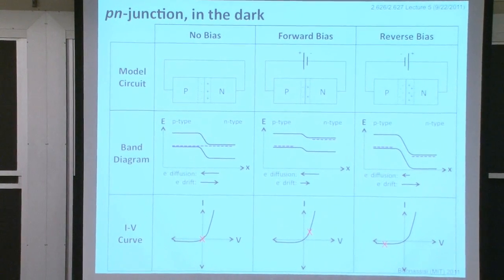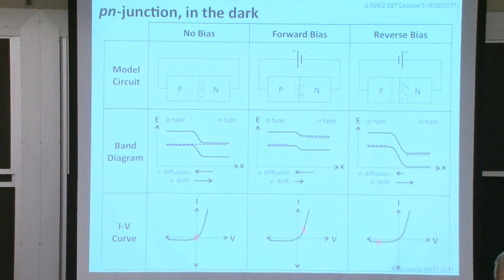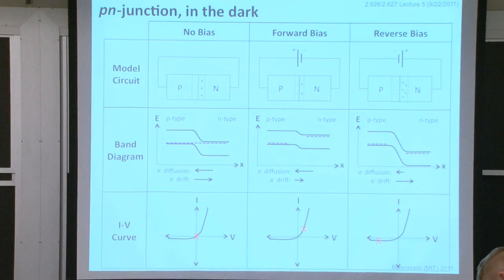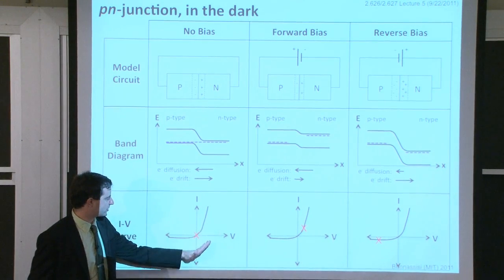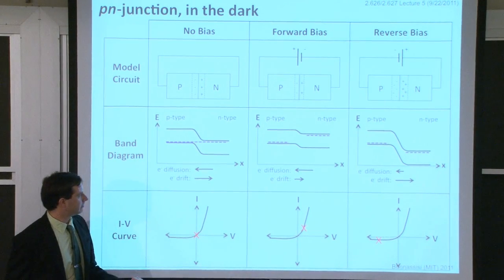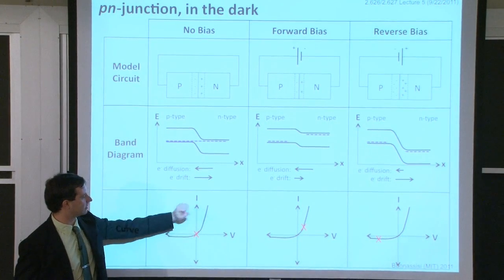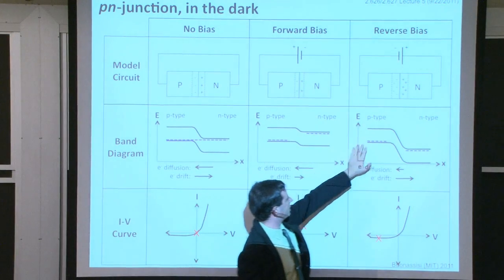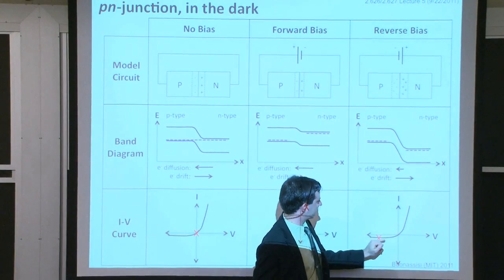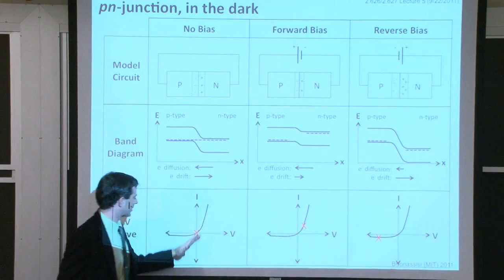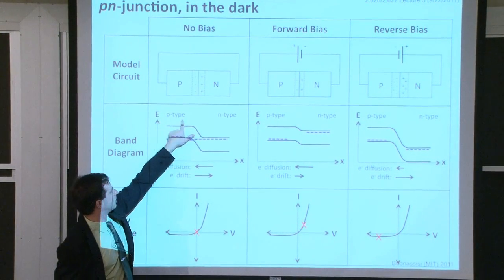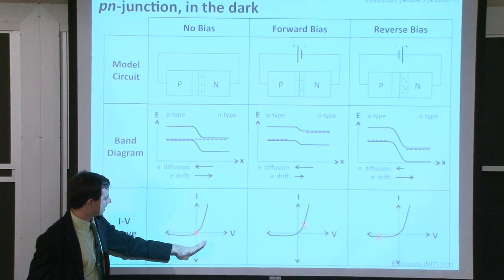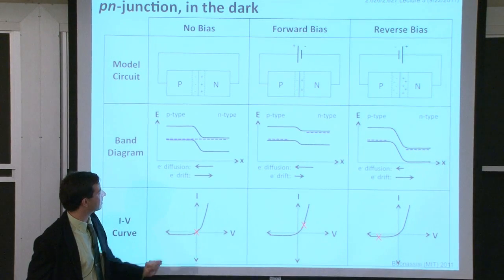Good. All right, so this is very positive. I see everybody has settled on the notion that illumination will shift our IV curve down because of the way we've defined current, that if current flows from left to right, that lands us in negative current territory. So that makes sense. If we shine light on our system and we have electrons flowing from left to right here, that'll put us into negative territory. So that shifts the entire thing down.